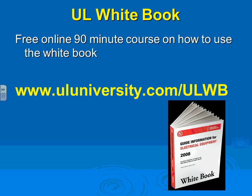The nice thing about the white book is it takes every article in a NEC code book. Say you have an arc switchgear, and you want to know which UL listing an arc switchgear goes under. So it takes the article of the NEC code book and the UL listing, and it references them. So if you're familiar with the NEC code book, you don't have to be familiar with this book, because all you have to do is, for example, go to the panel section, right?